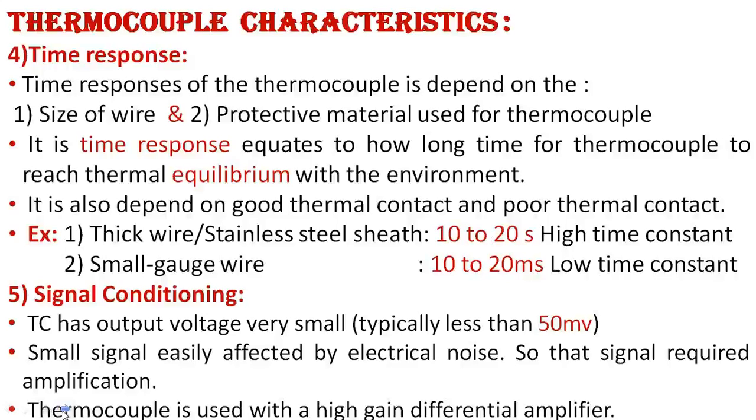Next concept is signal conditioning. The thermocouple has a very small output voltage, typically less than 50 millivolt. A small signal is easily affected by electrical noise, so the signal requires amplification. Thermocouple is used with a high gain differential amplifier.